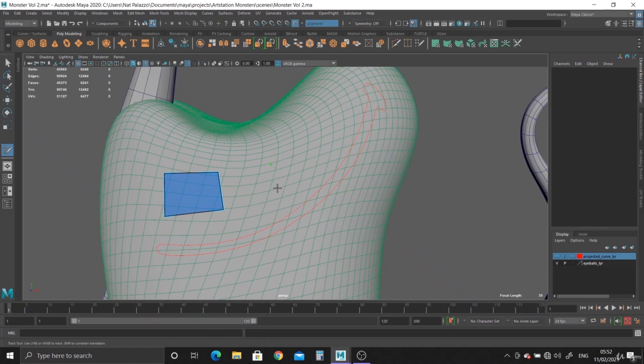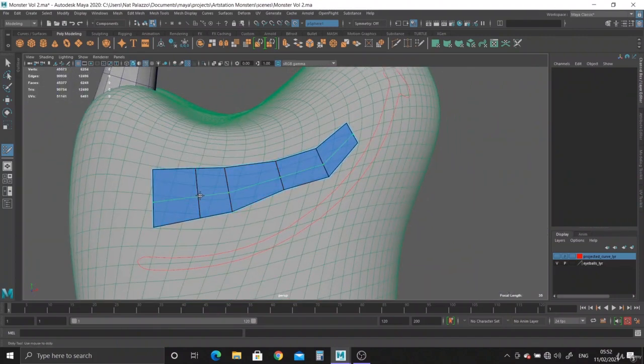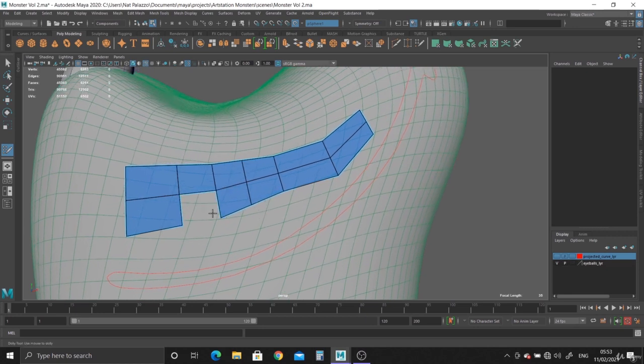And so click, hold down shift, boom, and you can actually just move these points around. You can move the edges and the faces, and basically what you're doing is you're sticking polygons onto the surface, as you can see. And if you hold down control, you can add resolution, shift control, you can delete resolution, and basically if you hold down shift in an area and it illuminates green, it means you're ready to add a polygon, and all you do is click on the mouse and there you go.